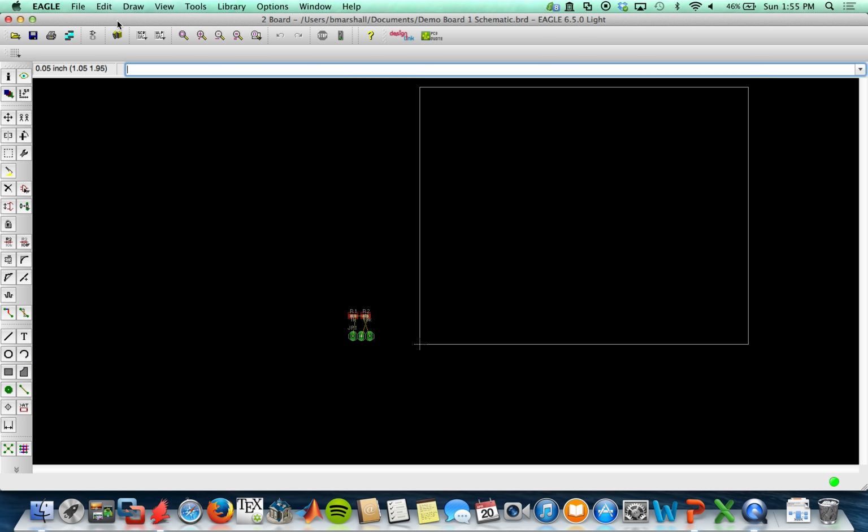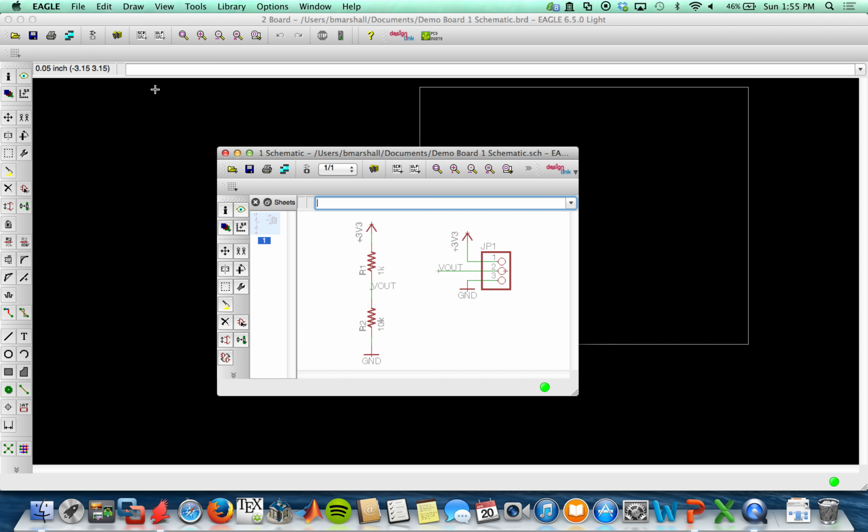So we've already completed our schematic that we can flip back to by clicking this switch schematic to schematic symbol. So we can see our schematic there, and so we see our 2 resistors, 1K and 10K, and our pinouts. So we close that, we go back here. So see this error that popped up?